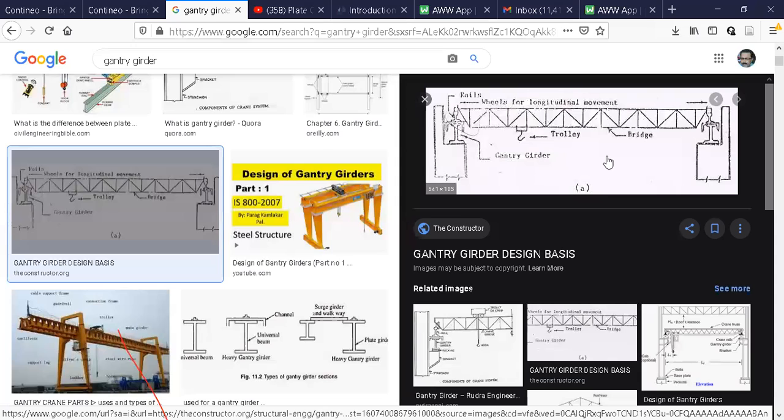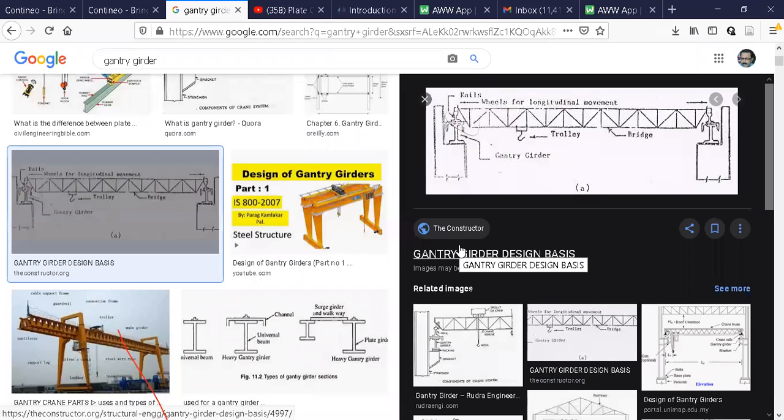See this. Again, on either side, a gantry girder is there. This is called a bridge or a crane girder. The crane girder is again resting on the rails. Okay, the weight of the rails must be considered while designing the gantry girder. So on two gantry girders, the crane girder is resting. So this much is enough. The profiles can be different. I'll show you that one. That will come here. Again, on the right side, it will appear now.